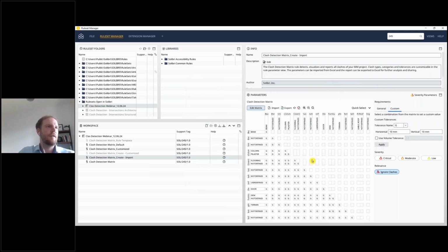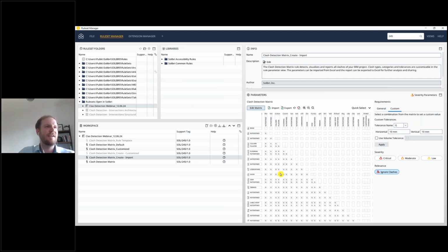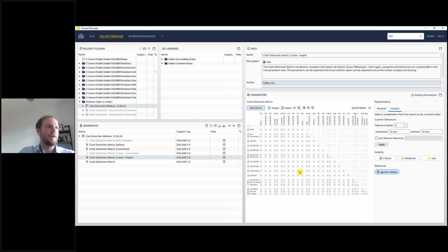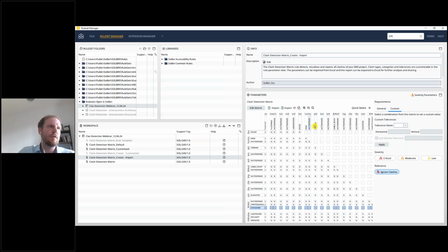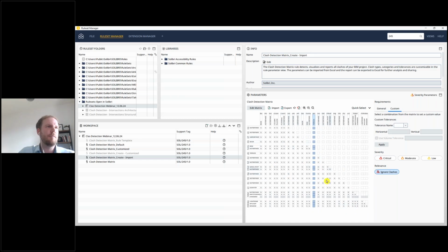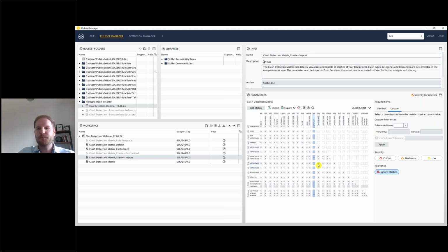Yeah, and now you have for every IFC entity also a predefined type, and then you can say, okay, for this predefined type, IFC wall standard, that should be ignored completely, or what else? I don't have that many predefined types here in my model, but yeah, I can do it like that in that way.